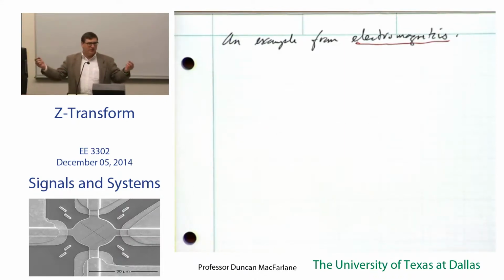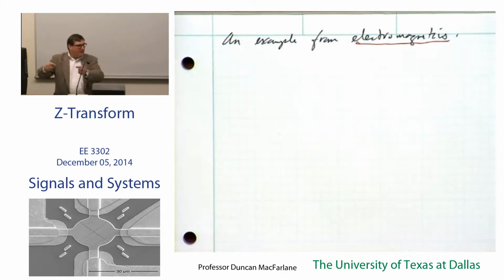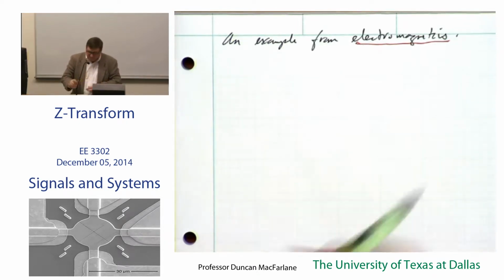And 3 feet of a transmission line means that the wavelength is smaller than that coax cable at a gigahertz. So in other words, if I send a 1 nanosecond pulse into a 3-foot long cable, I'm not loading up the entire transmission line. Okay? So let me model this.